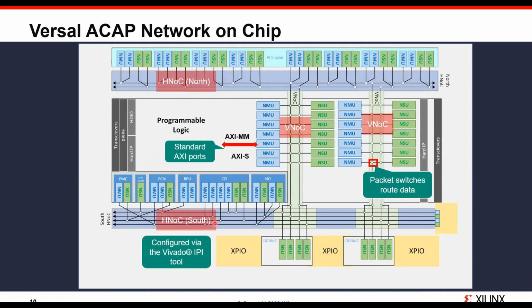So the NoC is basically made up of a southern path, the horizontal on the southern, which has 4 channels of 128 bits that are running across it. There's the northern path as well, the horizontal there, that is 2 128-bit paths that are running through it, and then a number of verticals, from 1 up to 4 verticals that are running 2 vertical paths as well. And again, they are tightly coupled down to the DDR4.